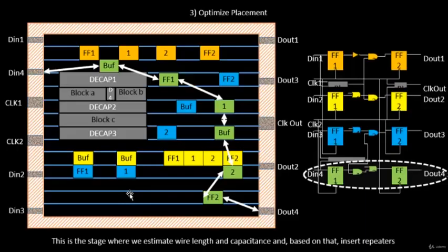Okay, so next we have to check whether what we have done is correct or not. Since the clocks are not built, we just check the data path over here. Considering the clocks are ideal, by ideal clocks we mean that the time required for the clock to reach flip-flop 1, flip-flop 2, any of the flip-flops is 0. So based on the ideal conditions of the clock, let's try to quickly do a timing analysis.